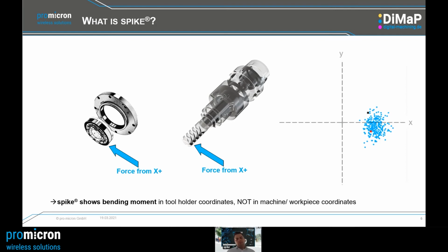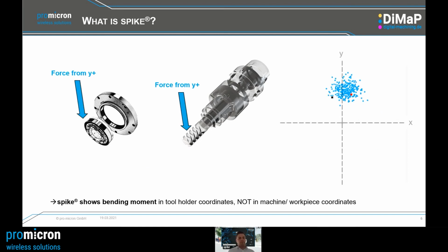And because of this, it is possible for us to visualize or to locate the cutting force direction on each single cutting edge. You need to know we have a coordinate system on the tool holder or in the spindle, and this rotates and the acting forces can be visualized. Now, please don't mix it, or you need to differentiate it from the X and Y direction of the machine tool or workpiece conditions. We look from the tool holder coordinates.